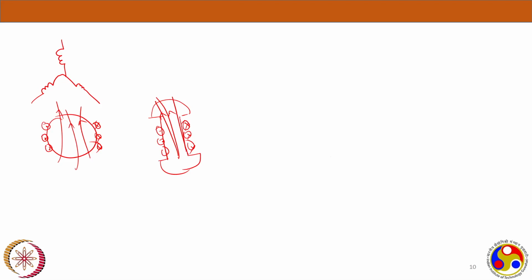And this particular rotor is called a salient pole rotor. So you will call this synchronous machine a salient pole synchronous machine. So based on the rotor structure, you will call the name of the synchronous machine. Now the stator winding is a three-phase winding. In terms of synchronous machine, we call this the armature, three-phase armature winding, and the winding on the rotor is just a DC winding, the field winding, as I said.